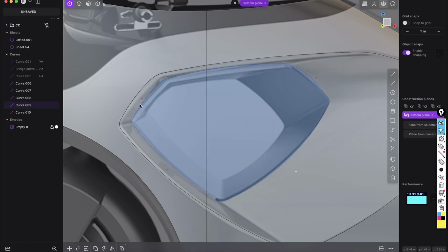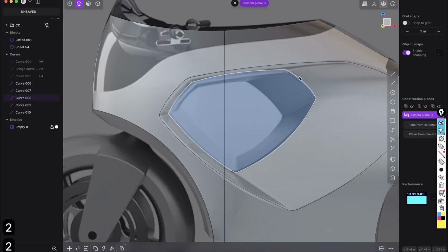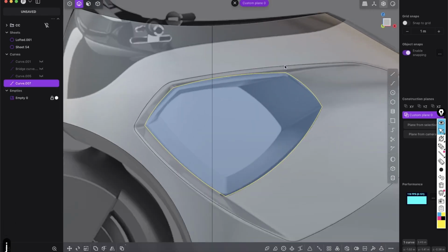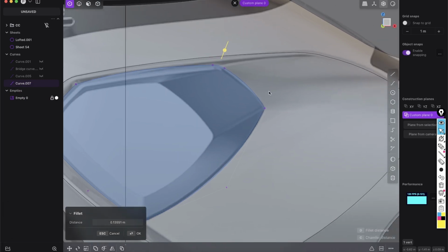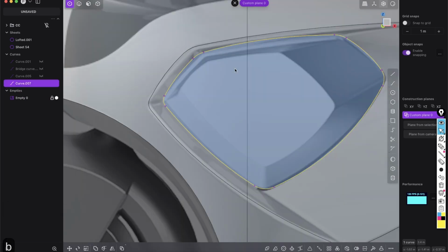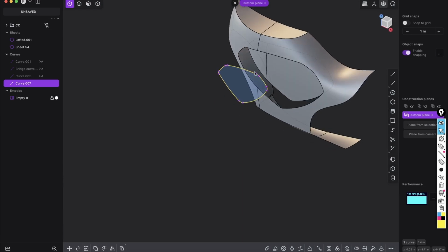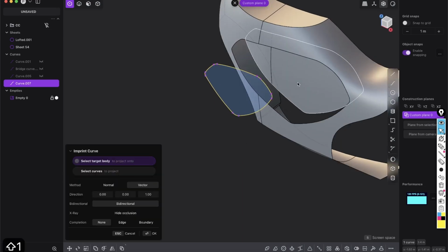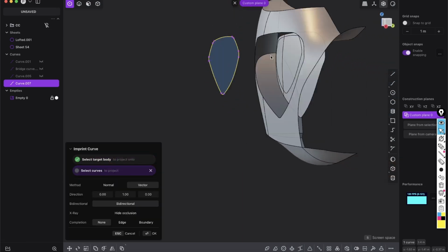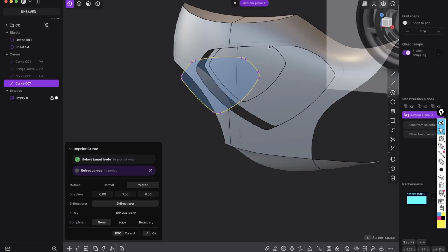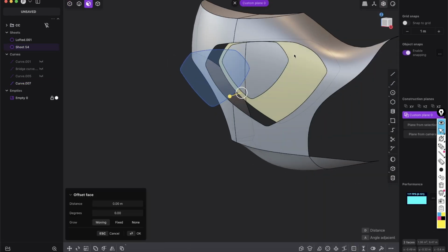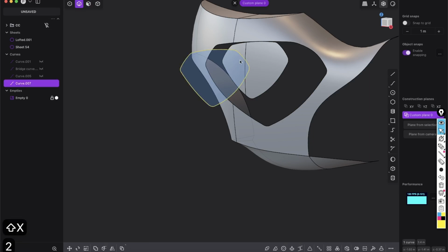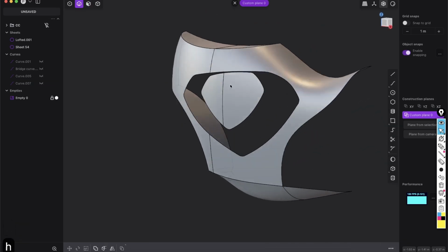So press 1 in points mode and just adjust all of the points here. And again, Alt click and join, and let's give all of those points a nice little fillet. Perfect. And again, curve is selected, Shift-1 to imprint onto the surface, and you see that just looks already amazing. Right click and delete the surface around because we don't need it. Shift-X, and let's hide this curve here.